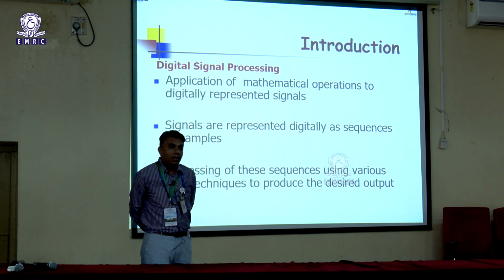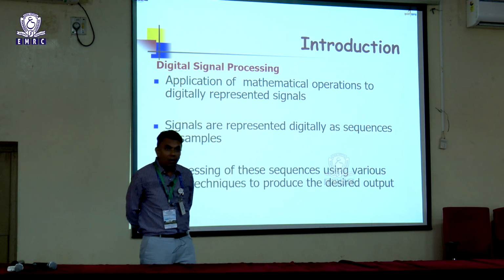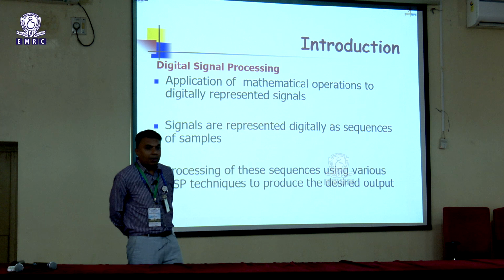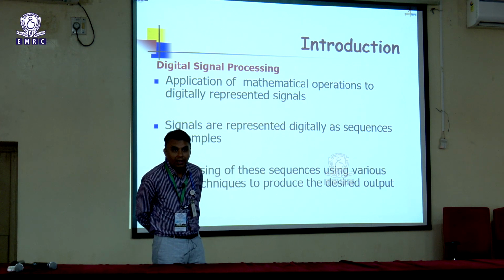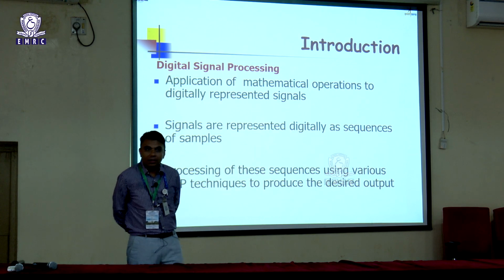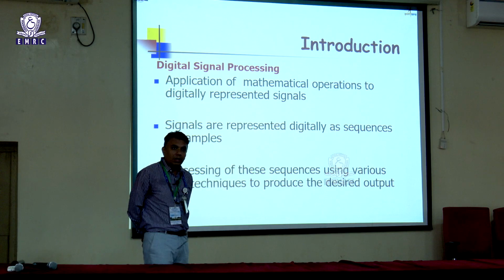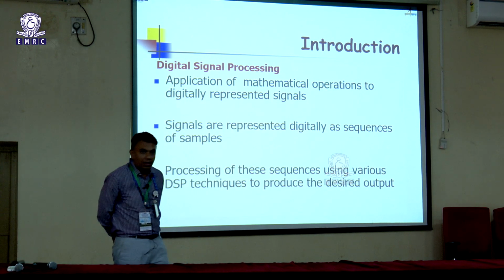One is to put a dedicated DSP processor chip inside our design, or we can place a soft processor inside the FPGA. But the problem with the soft processor is that it will occupy some part of your FPGA, and suppose your logic is big, we cannot fit the processor together with the FPGA. Then we don't have any other option but to go with the dedicated DSP chip inside our design for these applications.